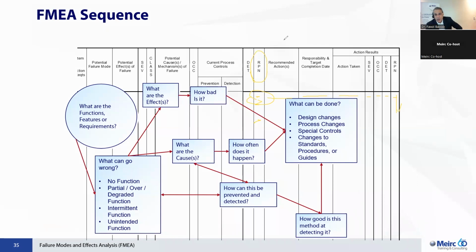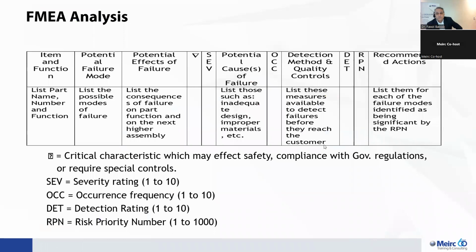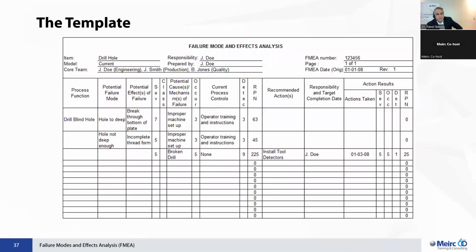which is the same function. So if you think here of an example, here is again just the template of the FMEA: function, potential, severity, occurrence, and then you'll need to fill here the numbers to look something like this. So here's an example where you can immediately see that here is the name of the function, here is the potential failure, here is the consequence of the failure, because this is what we're trying to evaluate.